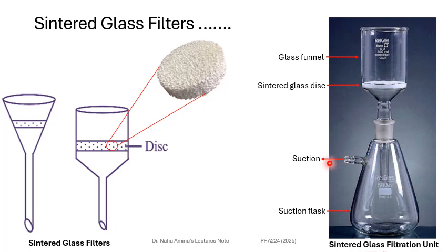And usually suction is provided using a pump. You can see this is where the pump is connected here, and when the machine is switched on, it provides a suction which leads to a high speed filtration rate. Okay, so that is how this one works. So remember, before commencement of any of these filtration operations, all this equipment has to be in sterile form. That is the only way you can ensure that whatever you process is sterile.